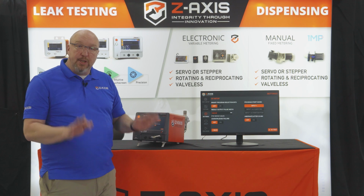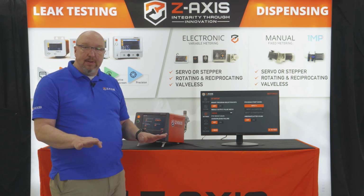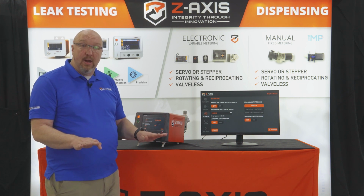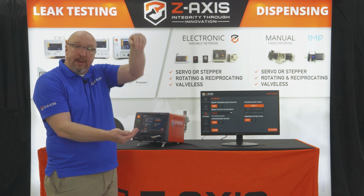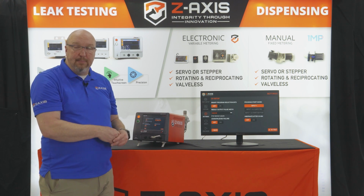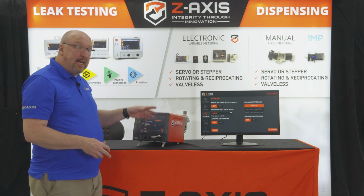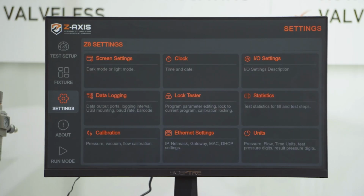Another nice feature is a two-hand safety or an anti-tie down, where 2 inputs have to be held together within 300 milliseconds of each other and held through any clamp time. This happens if you have a cylinder coming down to seal on a part. The operator can't start the test and stick their hand in under the cylinder and get pinched or hurt from that. So that's already built in based on the I/O. This is the screen that you'll come to activate that.